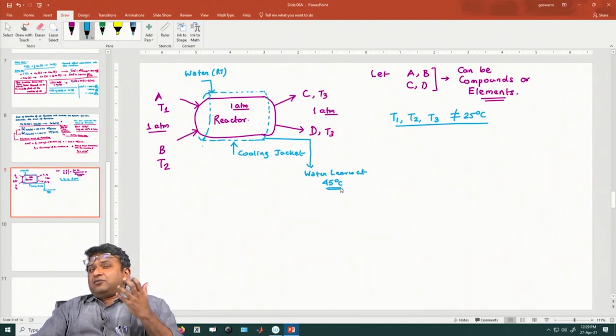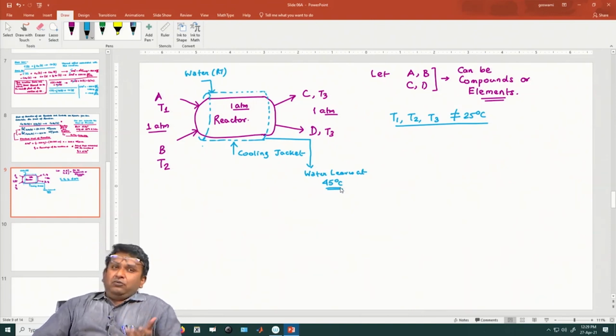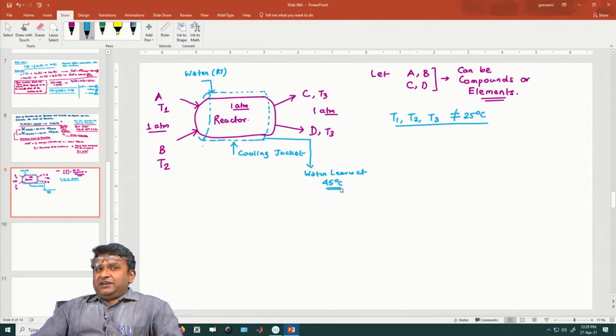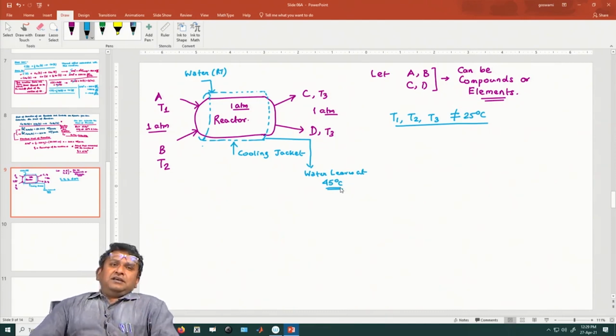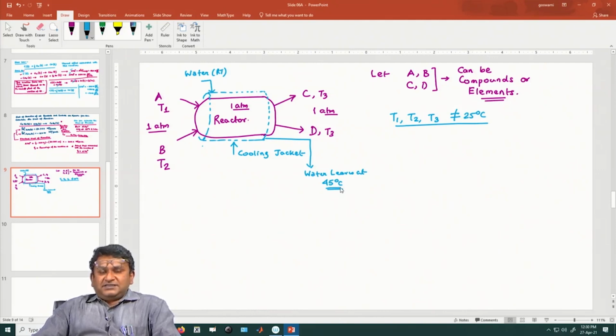Okay, so why do we take water liquid? Let us take ice at 0 degree centigrade, then we can harvest not only the sensible heat but also the latent heat. Nobody is going to give you all that. So, you will be given water, right, at whatever is the temperature. So, these are actually design problems: if you have a plant where there is seasonal fluctuation of temperature, which is very common in a country like India, how essentially do you handle your water supply system?